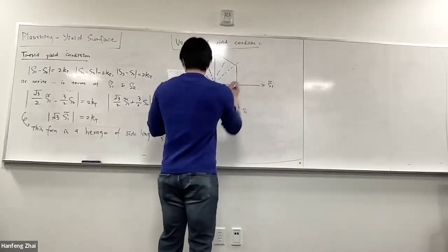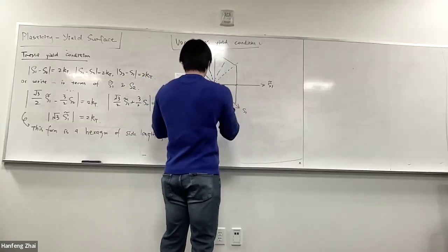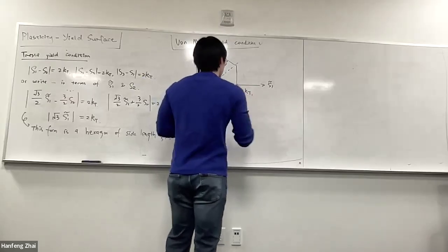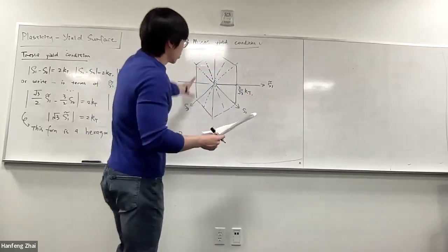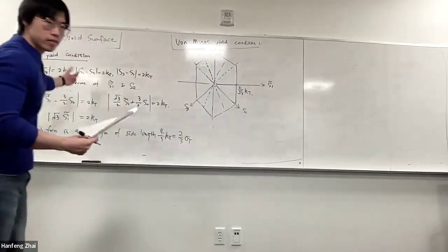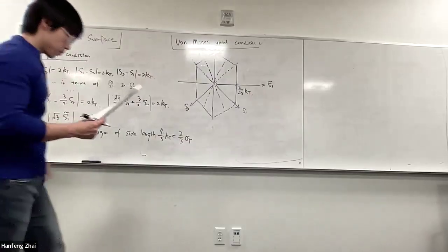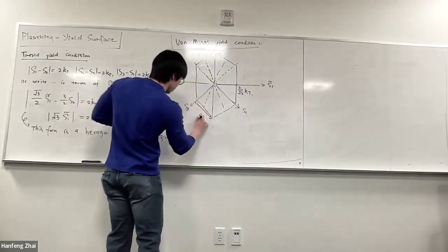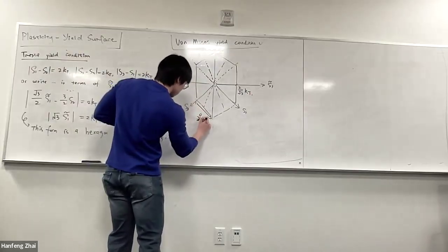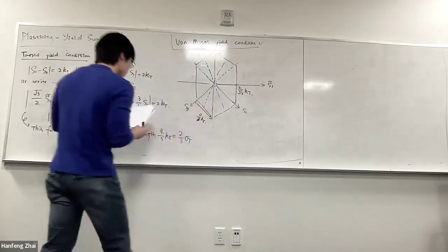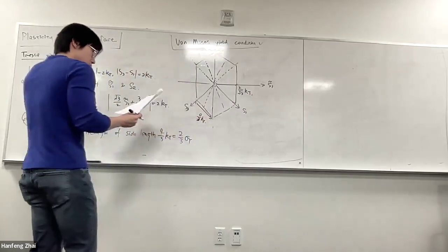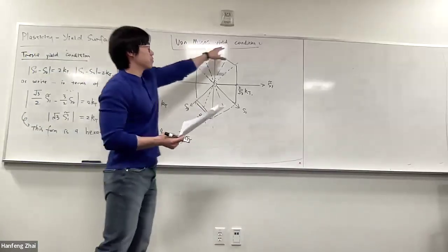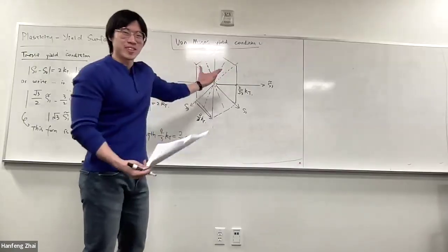And the intersection of the two axes would be 2 over square root 3 kt, right? And this will be what the Tresca yield surface looks like according to this definition of mathematical construction. And this side length is 4 over 3 kt. Okay, and since I didn't wipe out the von Mises yield condition, I still preserve the text.